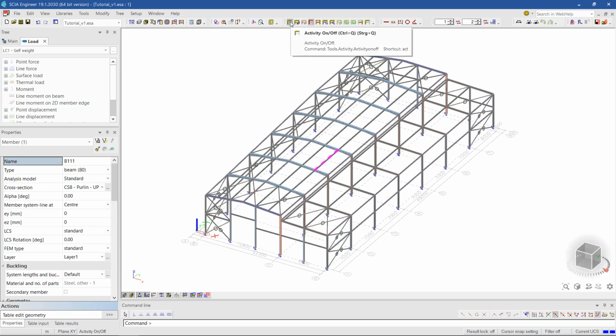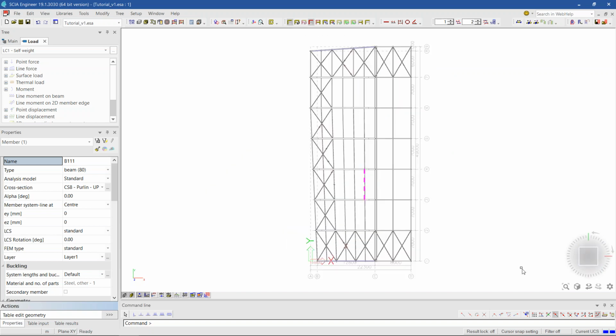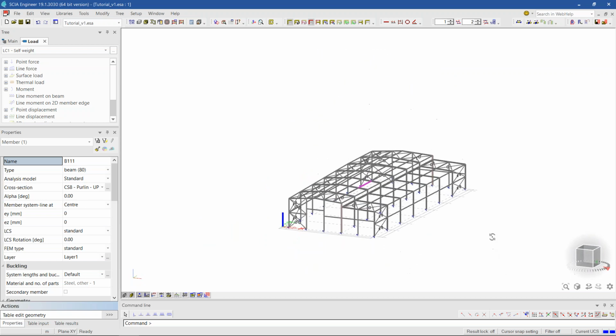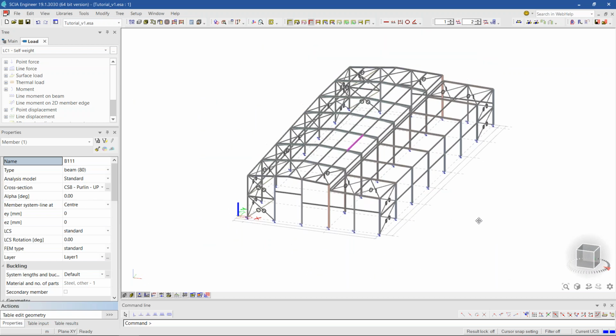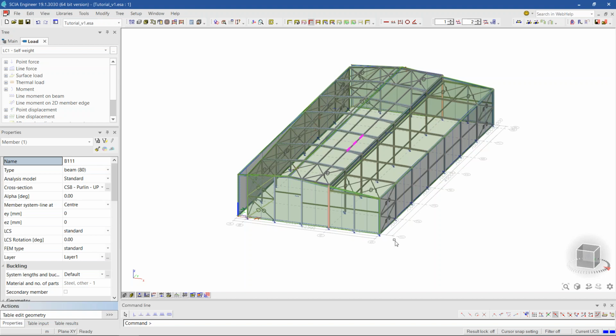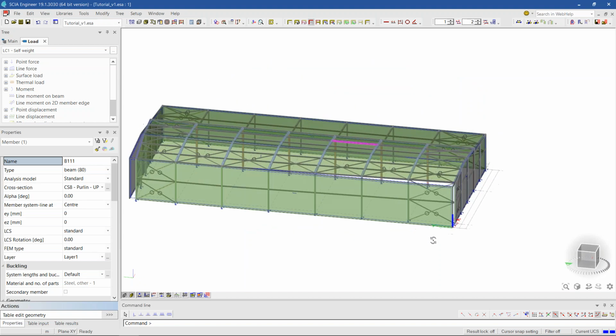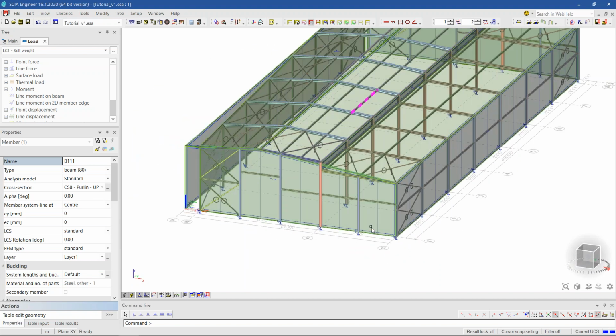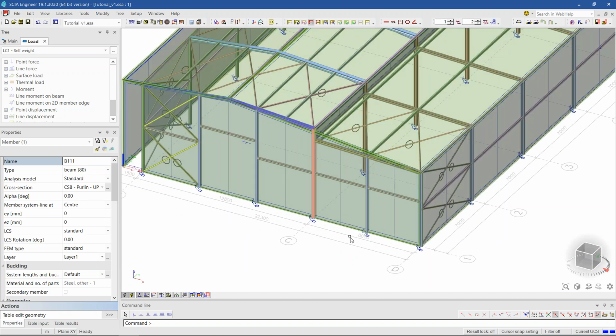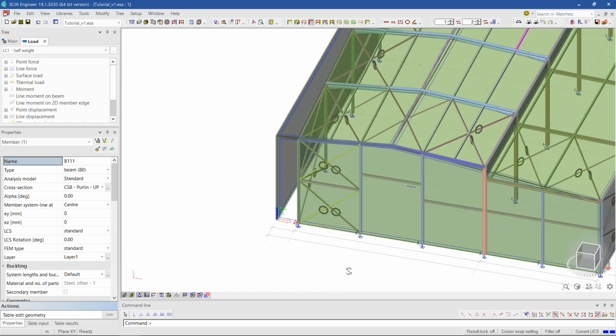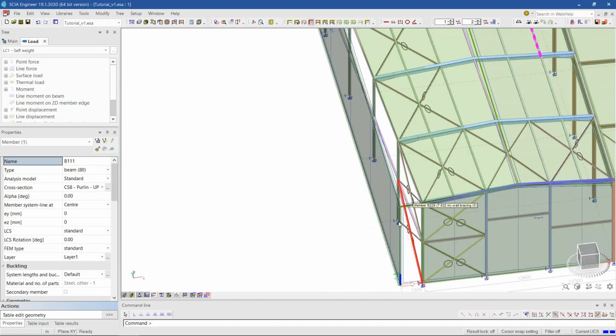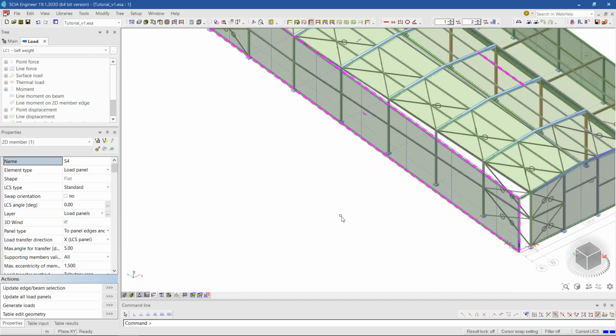So what I've done is, because my structure is more or less regular, in fact, it's close to a rectangular shape, and the roof is not so different from a dual pitch roof. What I have done is I have modeled load panels around my structure. And the nice thing about load panels is that they distribute load not by contact to your elements. So it means that even though the element is located here, this load panel is able to distribute load to it.